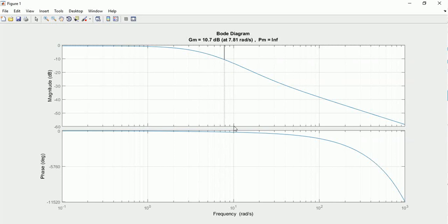So then we are going to design a second order filter whose cutoff frequency will be around 10 radian per second, and it will have complex poles with no resonance. Why we don't want resonance? Because we don't want any frequency to be amplified in this region.